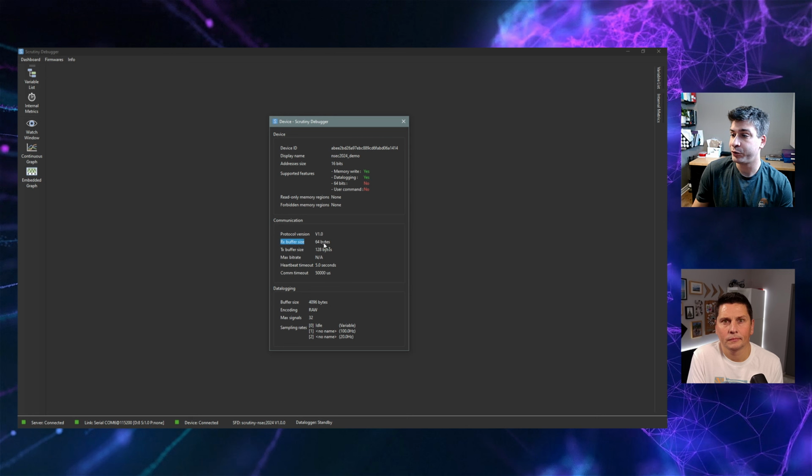So there are two transmission buffers that are assigned, one for reception, one for transmission. So 64 byte, 128 byte. It's lightweight. This is what, as an integrator, I put in my device. I could have used a bigger buffer. All it gives you is a better refresh rate if you give it more memory. Okay, so that is all the configuration of the embedded library.